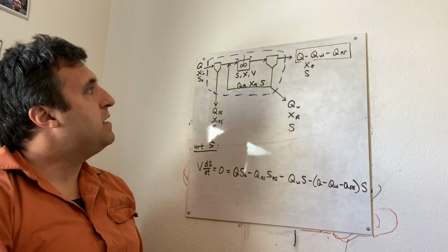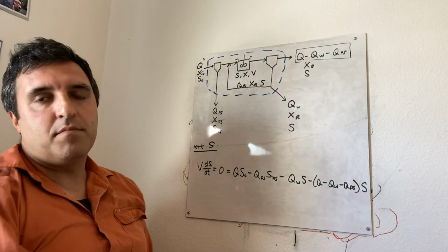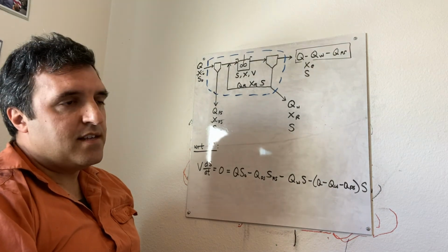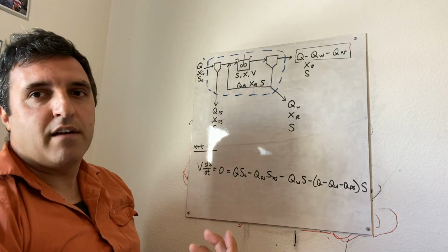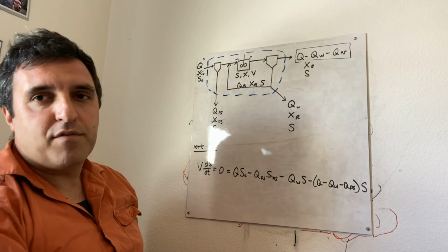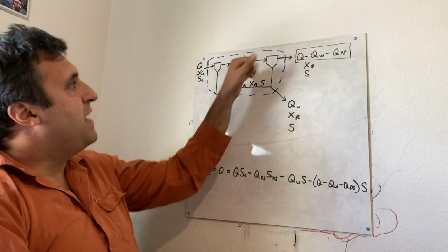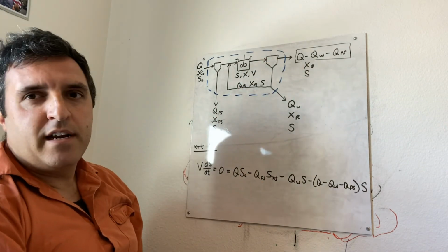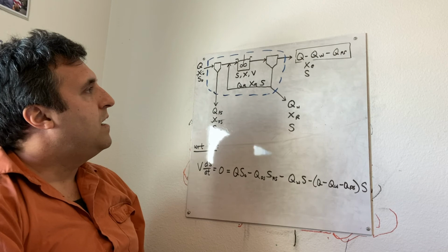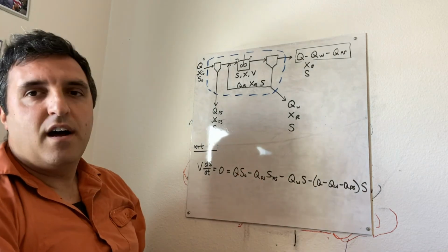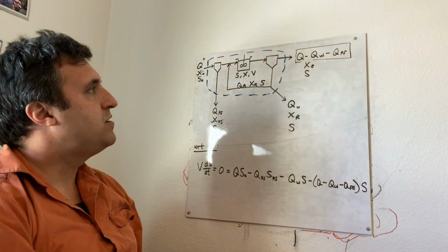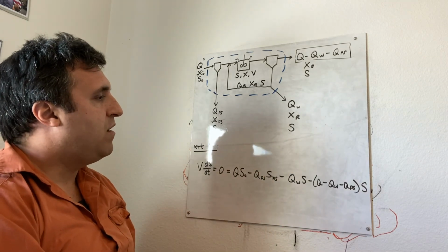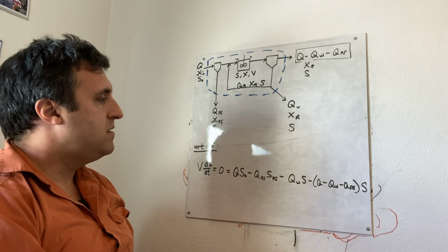And if we're assuming complete mixing conditions, as indicated by the symbol there, complete mix inside the aeration tank, then the substrate concentration is uniform throughout the entire reactor, and it's equal to the effluent concentration. All right, so if the effluent concentration is S, and you have liquid-solid separation here, it's really not affecting the concentration of remaining substrate so much. So we can call that equal to S at all points in our mass balance.